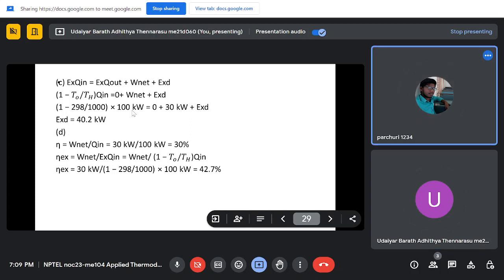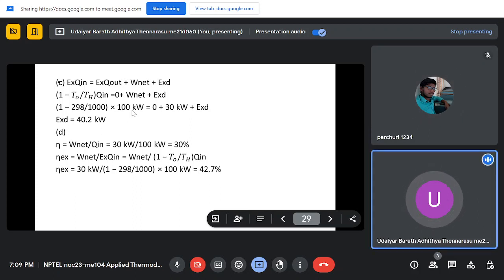That's why you need a highly efficient compressor, and you need to reduce friction in usage. You can only reduce it to a possible limit, and you need a more efficient compressor and a bigger heat exchanger. You can only try to reduce it, because you cannot totally get rid of it: exergy, entropy is generated in the heat exchanger, because heat transfer will only happen if there is a temperature difference.